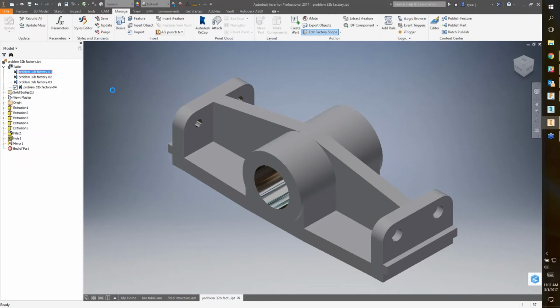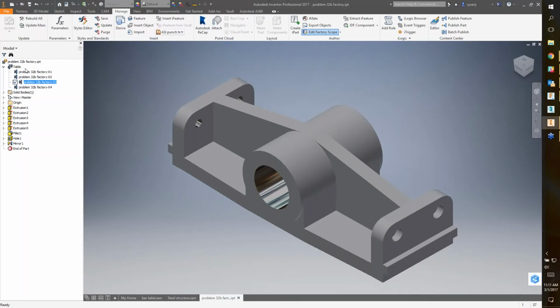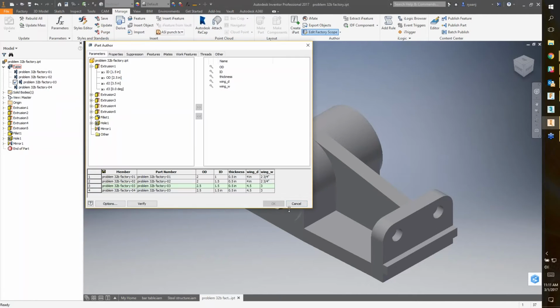The last thing that I want to look at there is just the configurations, the iParts. So in Inventor, we basically have a table. We can set up multiple size or parameter options, even have components suppressing and unsuppressing as needed. This is a great tool inside of Inventor. So here we have our family table.